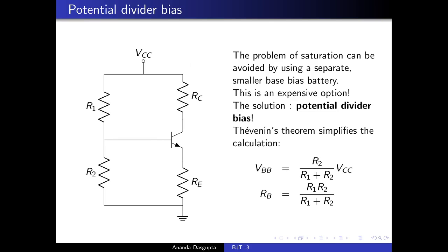Of course, we still have to connect the signal and take the output to make this a proper amplifier. But this circuit is really one of the crowd favorites because this has simple operation, simple design, improved bias stability, improved beta independence, as well as a low expense because you're not using two batteries, you're just using one. So in the next lecture, what we are going to do is take a look at what happens when we take an amplifier circuit like this and actually connect the input signal. So we will be discussing the proper amplifier action of a transistor circuit